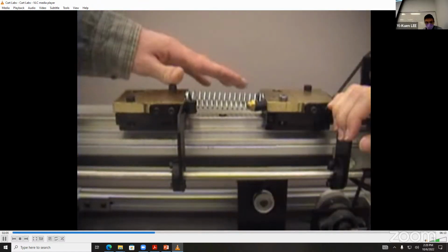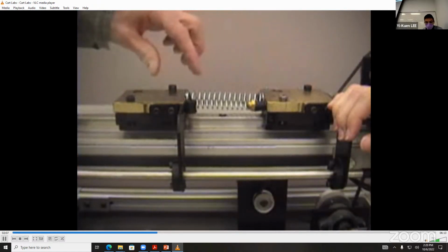As we said before, the Scotch yoke output is pure sinusoid, and it appears that way when we plot the measured data. With the slider crank, you can see it's fairly close to sinusoid, but because it has a second frequency component, we have this delay type action in the low part of the curve, and a slightly quicker return action.